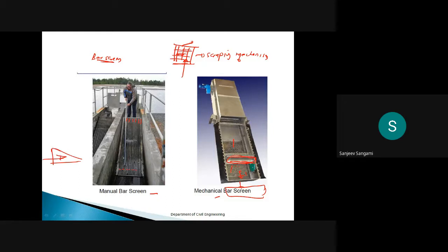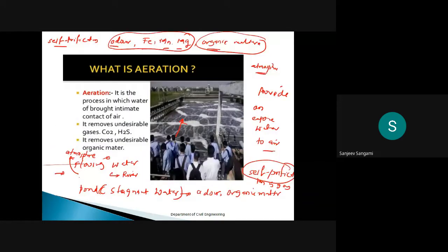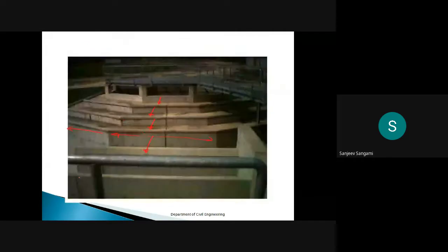It is just screening it. We are not allowing particles to settle here. Normally we use one word called retention time. Retention time is nothing but allowing the water to stand for some time at a point. At this point we are not allowing it to stand, but in the process of sedimentation, we are allowing the water to stand for some time.